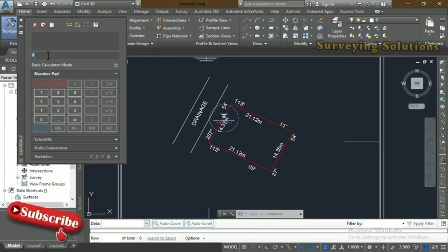Now we were talking about how to get the scale factor, right? Good. Remember that we have 14.37 here as the designed length, whereas when we moved it from PDF to this CAD, we're having 1.409. So we need the scale factor. To get the scale factor, it will be the original distance divided by the distance you got when you moved it from PDF to CAD.